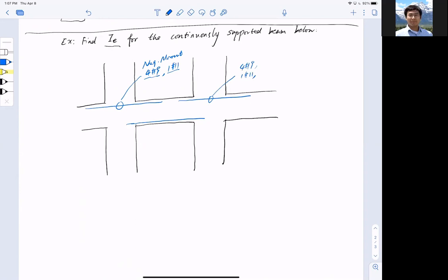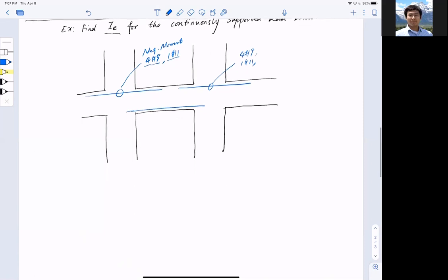So that is the reinforcement strategy for the ends. Now in the middle span here, I provided 2 number 9 plus 2 number 8. So that is in the middle span. The clear span length here is 25 feet. The clear span length here is 25 feet. So this is the cross-section detail.